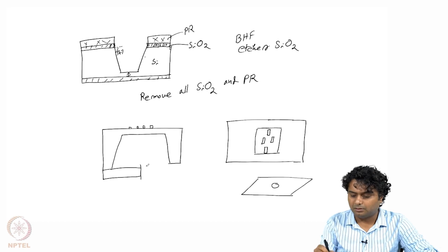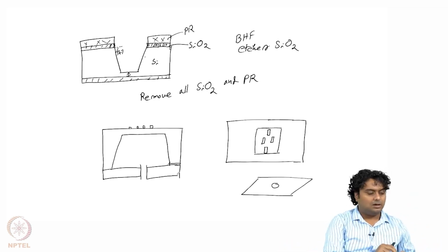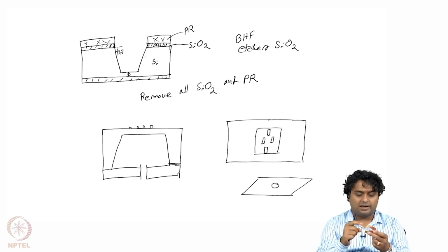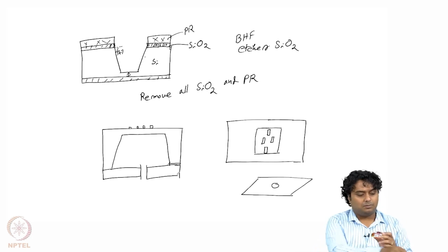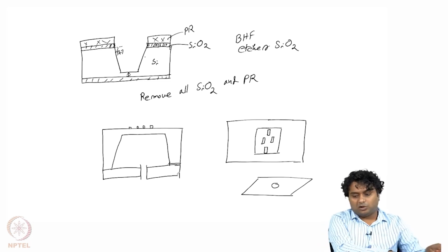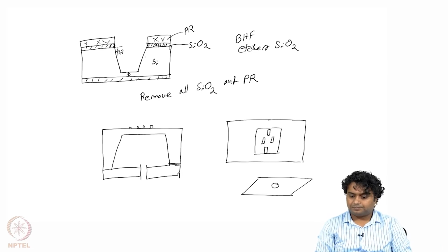We bond this wafer to the top wafer. So all the piezo resistors and etching have been done on this plate, and then we have a cavity at the bottom, and then we just take another plate and stick it together or clamp it together by bonding, and then we have the full pressure sensor.